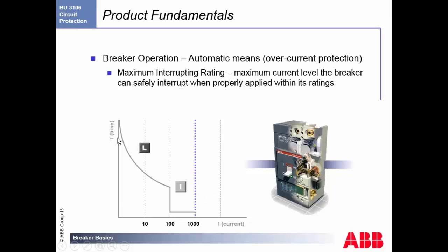So as you can see, it's very important as you are looking at these breakers and speccing out these breakers to know exactly what load and the application you're looking at. Again, if you're looking at a spike, you're going to employ the L, and then you're going to make sure that your time is fine before it levels off, and hopefully your current stays below the instantaneous. If it goes above the instantaneous, we're going to open right away, and if you go past even our maximum rating, then we're all in trouble.